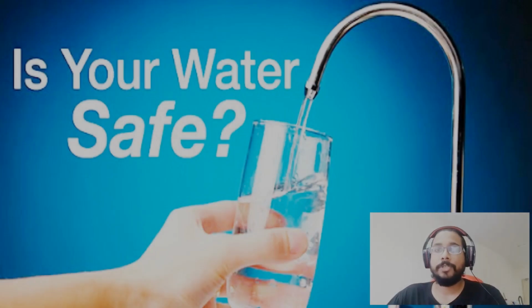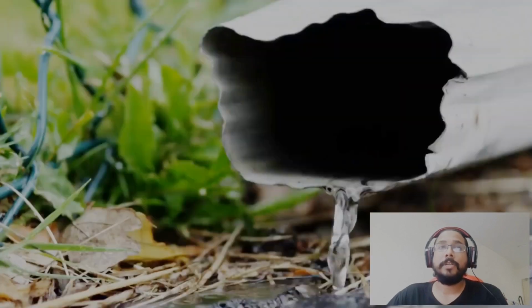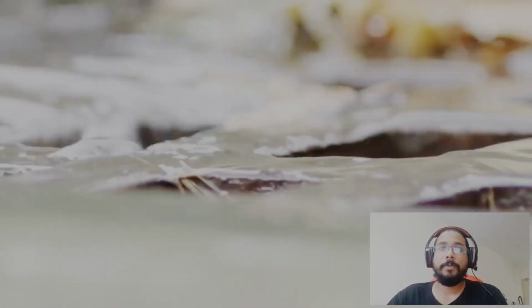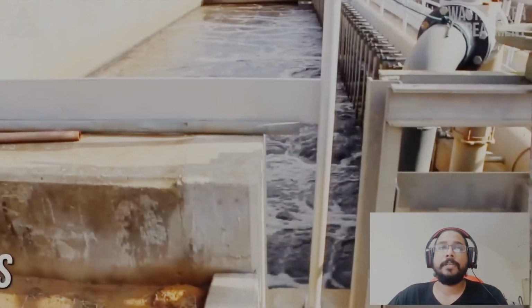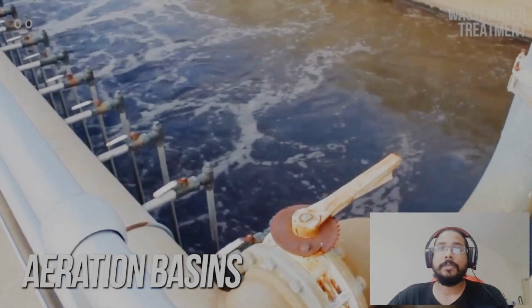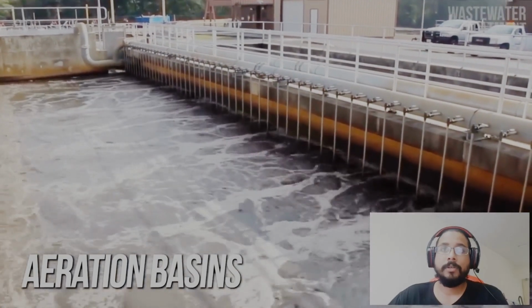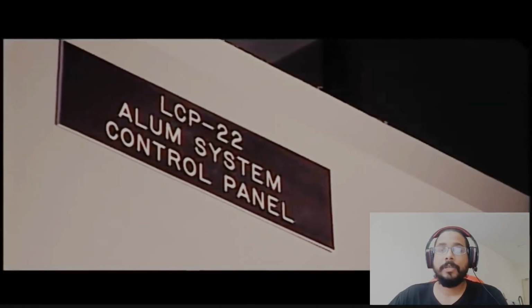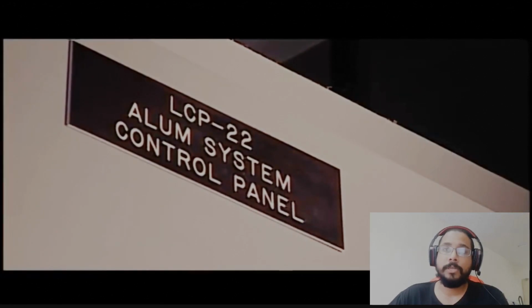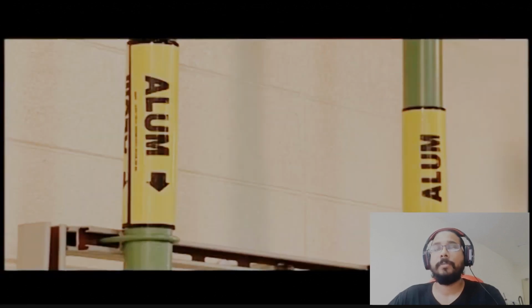The topic I have chosen to design my water treatment technology is the water treatment process. The water treatment process involves 6 stages or 6 steps. Step number 1 is aeration, which is bringing air and other gases in contact with the wastewater. Step 2 is coagulation, which is adding chemicals to water that can increase the force of attraction between the suspended solid particles within the wastewater.